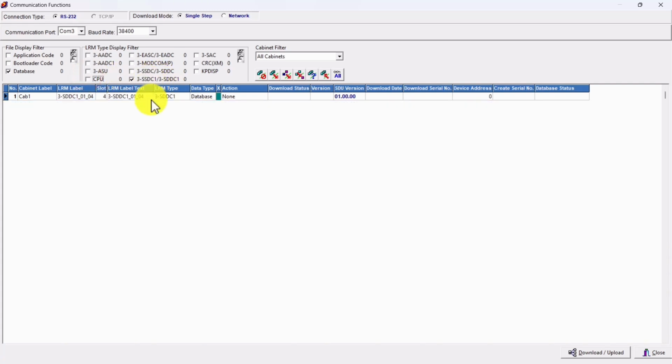However, if that point had changed an address, now the CPU needs to know because it didn't know that there's an extra address to this system. So now we need to adjust the CPU. So hopefully that doesn't confuse you. Just in short, if you make any new changes to the system, both cards need to know. If you're just making the same changes to the system, swapping out a device for a device, only the loop controller needs to know.